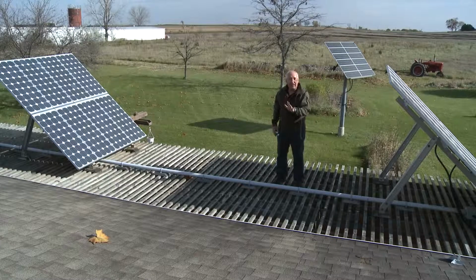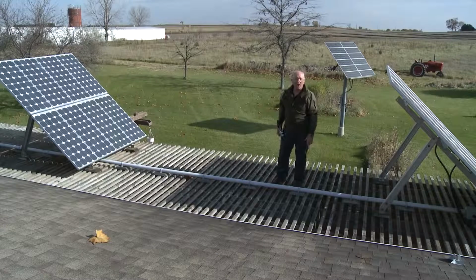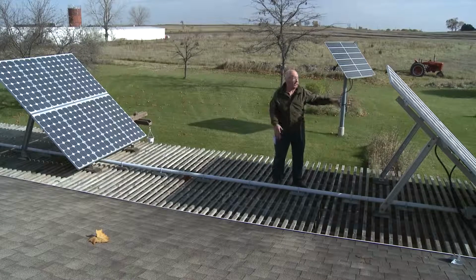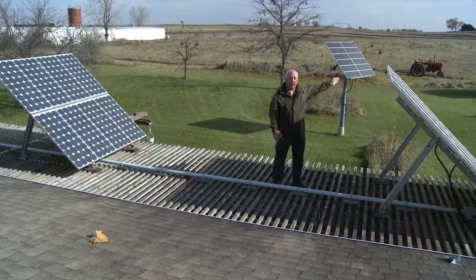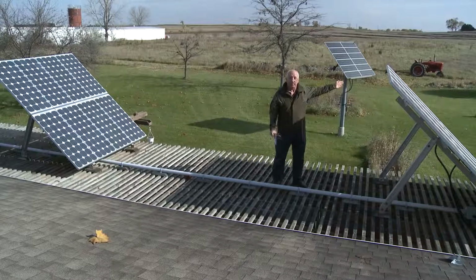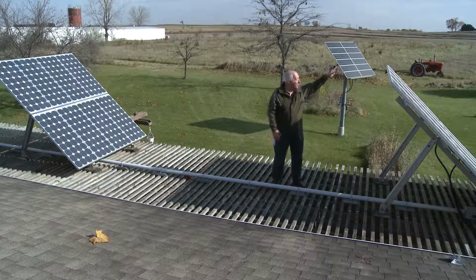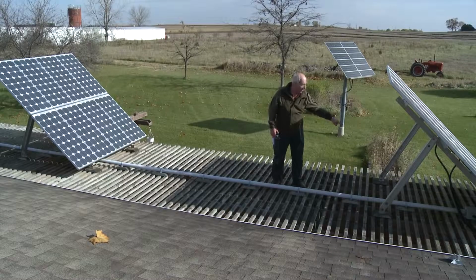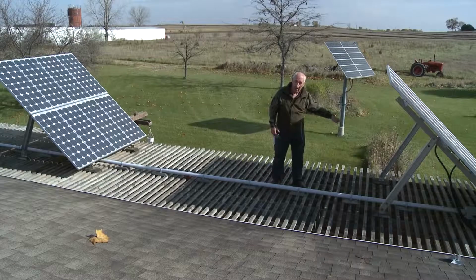Now I have a different angle though. The angle I have now is 90 minus my solar azimuth. Well, it's good and easy in this case because with solar azimuth at 45, 90 minus 45 equals 45. So now from where this line came down and I had my 90-degree angle here, that's also the point of my second flat triangle.